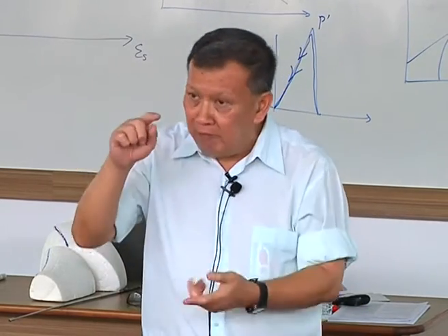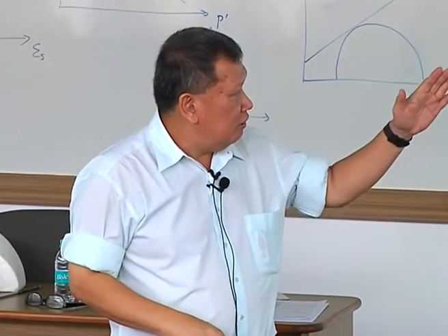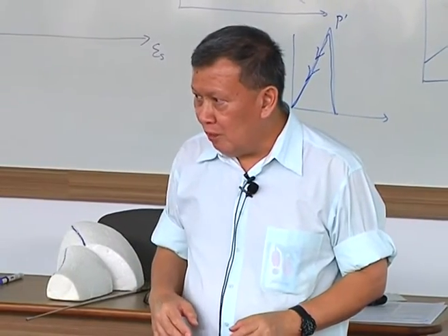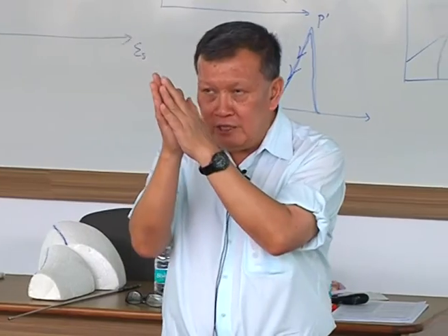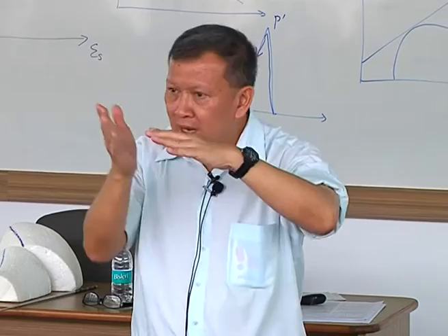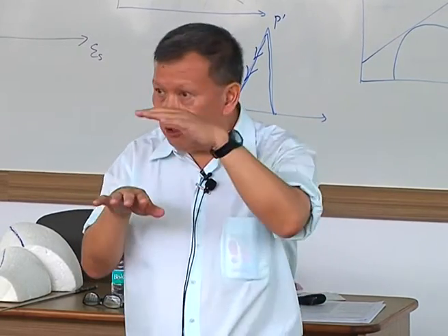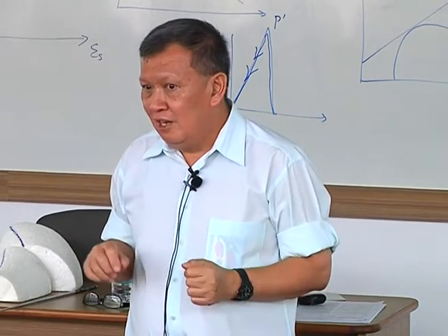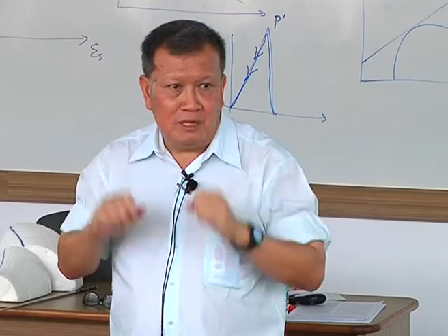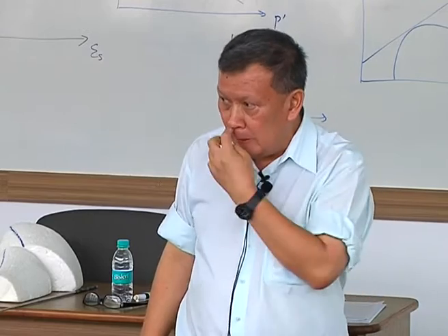It's an enlarged platen, but we also use a short sample. If you look at the inclination of the slip plane, most of our samples have a 2:1 aspect ratio, and there is room for the shear band to actually occur. But if you use a short sample, you actually inhibit the formation of the shear band. But when you have a short sample, you have to be very careful, because any kind of end friction will actually affect your result. So you must make sure that your friction reduction is very, very effective at the ends.